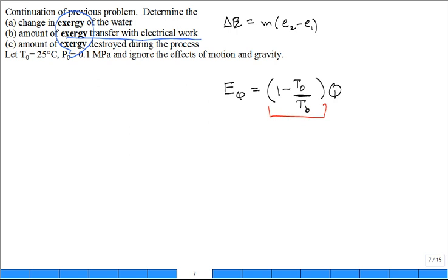Okay, let's do this. Any exergy transfer with the work? It's just the work. With what multiplying? 1. It's a 1-to-1. If I have 1 kilojoule of work transferred, I have 1 kilojoule of exergy transfer. The only time that that's not true is if I have to subtract off the non-useful component of boundary work, pushing back the boundary, the atmosphere. That's the only other time. But here I have electric work. It's 100%. So guess what the answer for part B is?